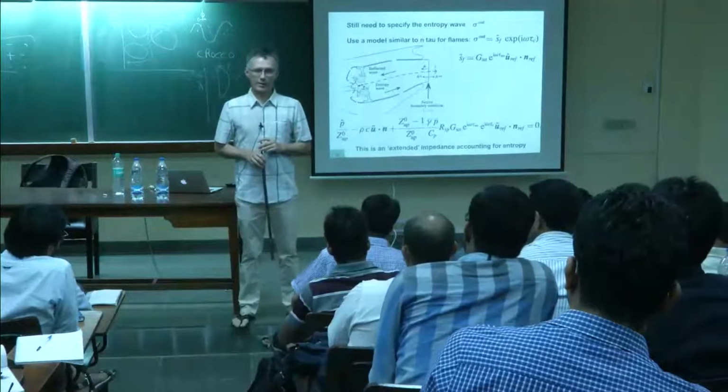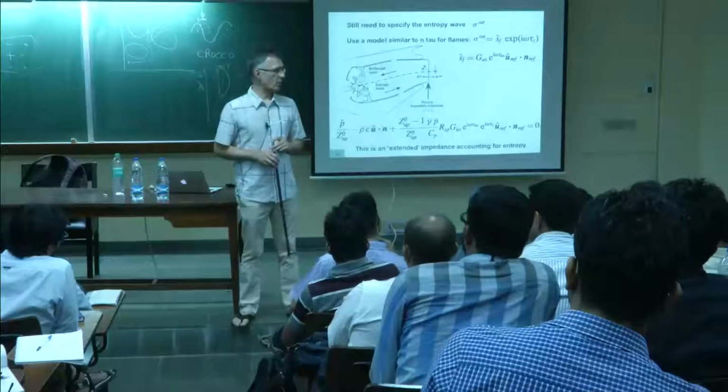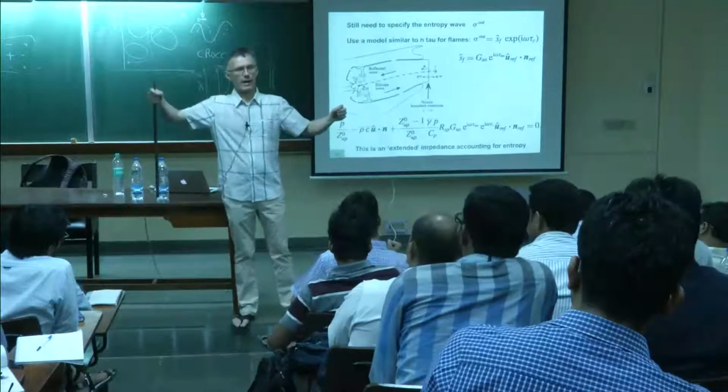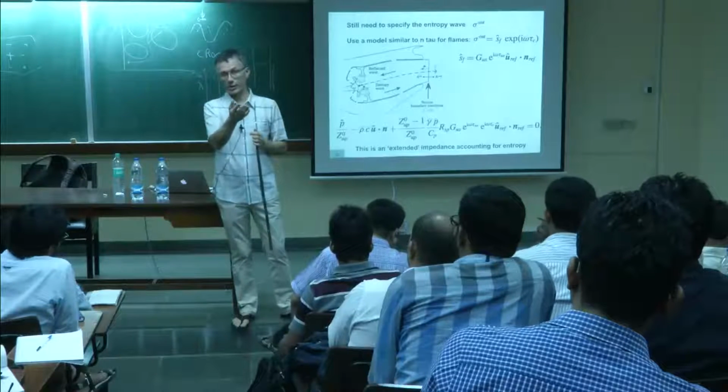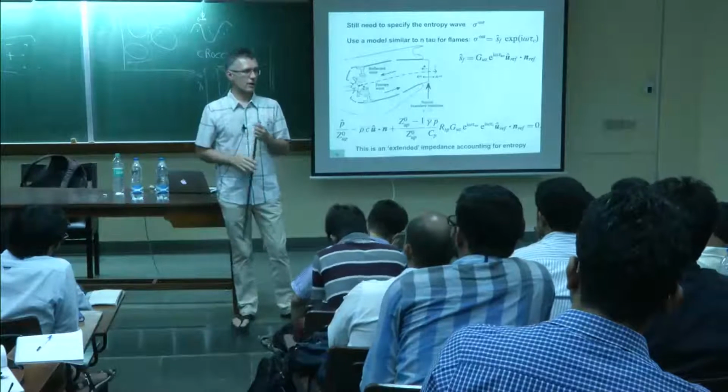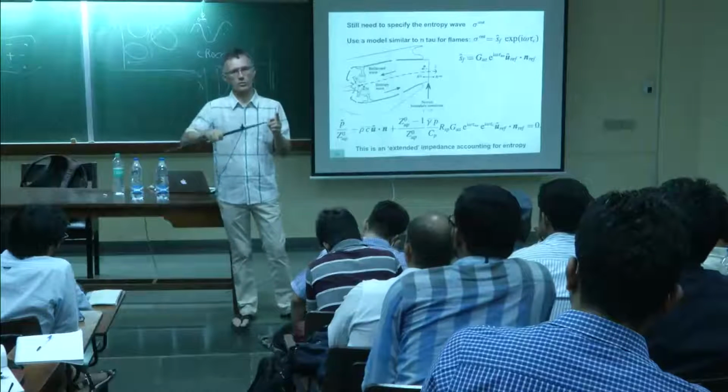Rocket motors are a completely different business. One of the main problems is that the flames are very long, and you cannot use compactness assumptions. And the other problem is what I've shown actually at the seminar 2 days ago, is that the modes are not longitudinal, but they are transverse.